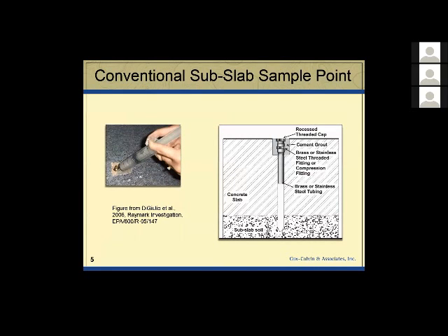This requires cementing around the probe and between the probe and the concrete, and it does have some limitations. You can see that the cement going around there is a relatively small area. They have a tendency to break loose, including to the author here, and to probably about everybody who's tried this. You have to wait for the cement to set up and typically come back and sample on the next day. You normally would not be able to reuse this hardware.